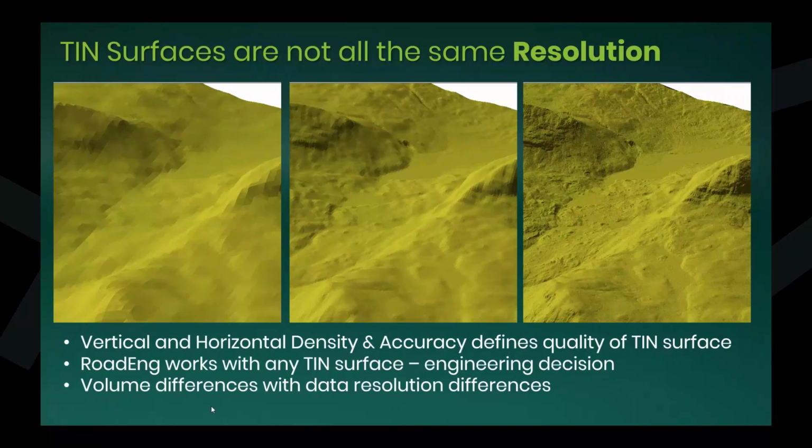In the remote sensing space, it's something that we occasionally see, and something folks should avoid. Just because you have a DEM with a 1 meter point spacing doesn't mean it's good data, especially if that DEM was generated from a 30 meter DEM before it. So upsampling doesn't improve the quality. And then there's the original accuracy of the surface too.